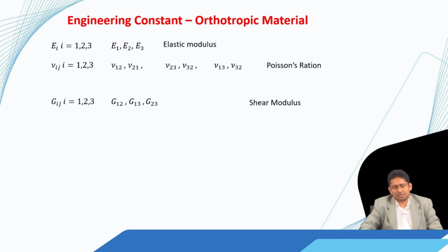Now we generally do not directly derive those 9 independent terms, rather with the help of experiments we derive some elastic constants which are also 9 in number, and then from those elastic constants we find out the components of the C matrix and the compliance matrix S.